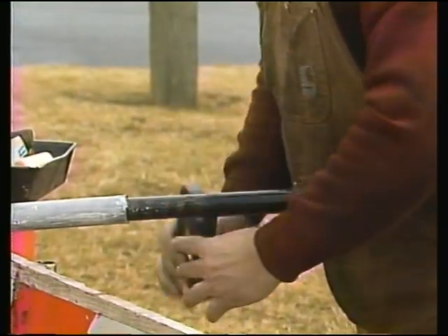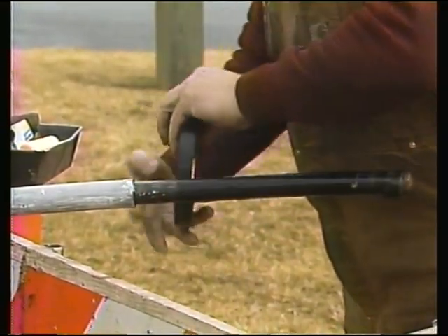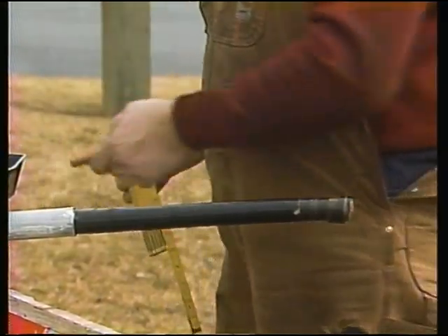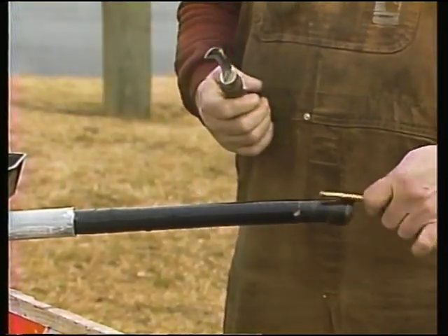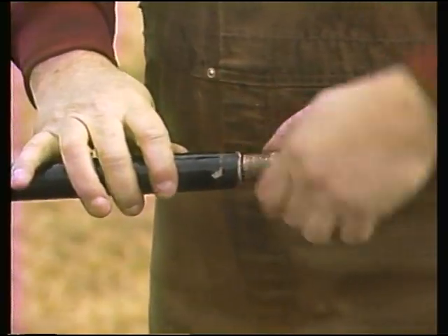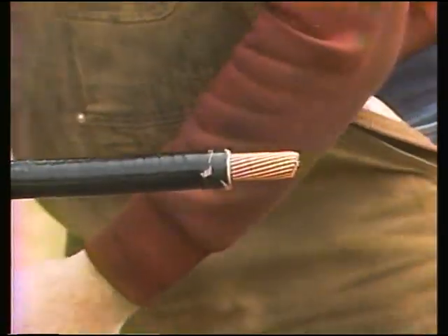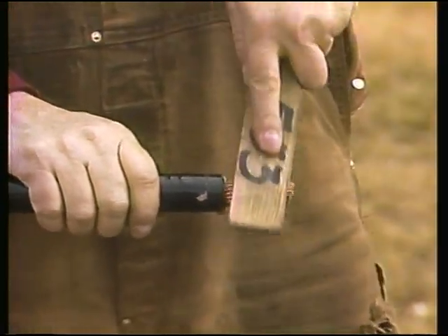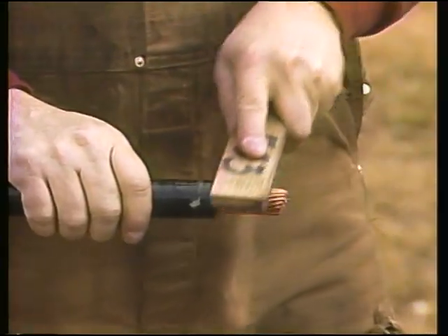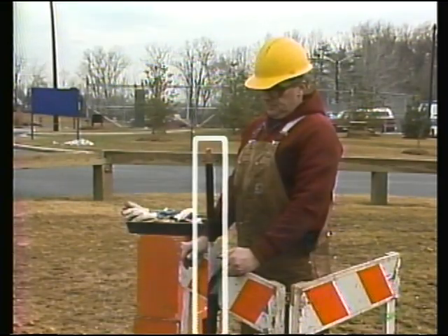Now, to protect the paper insulation below, a protective tape is applied over it. Next, he measures the connector and marks the appropriate distance on the cable insulation. He then removes the remaining cable layers, exposing enough bare conductor to install the connector. The conductor is then wire brushed. Next, the cable is repositioned to make the conductor end more accessible.